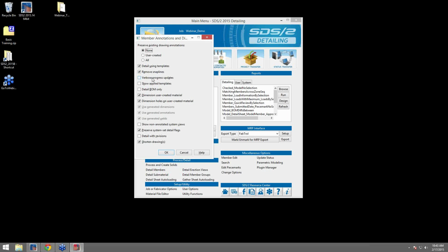The reason this option could be useful is if you're developing, modifying, or creating your own templates, and possibly you've made the rule maybe a little too generic, it's providing too many solutions, it may take a little bit longer for that rule to apply. With this option checked on, you'll be able to visually see within the progress which template is being hung up on, and then you can go back and figure out where your particular mistake might have been made.